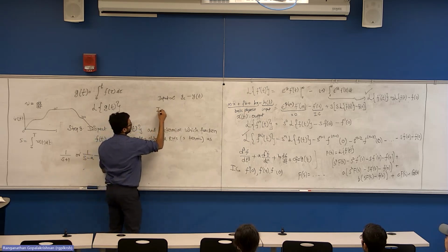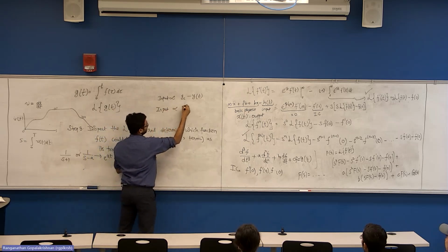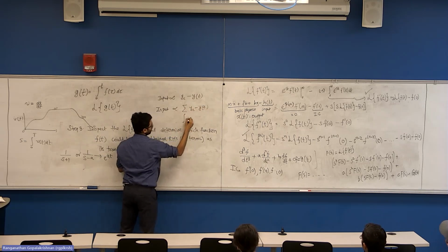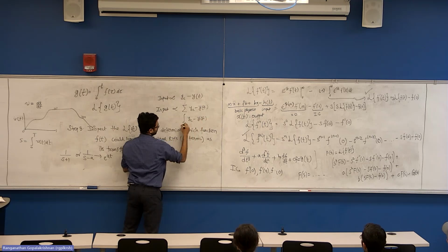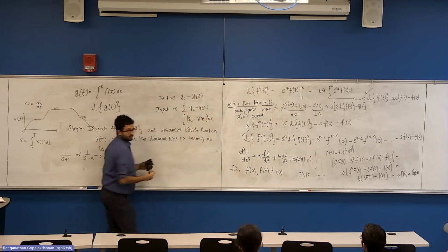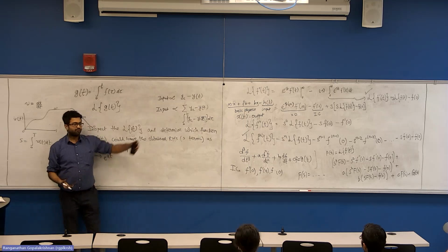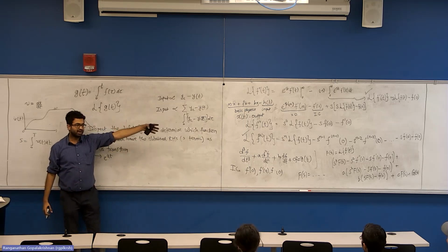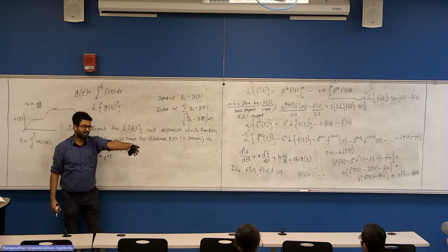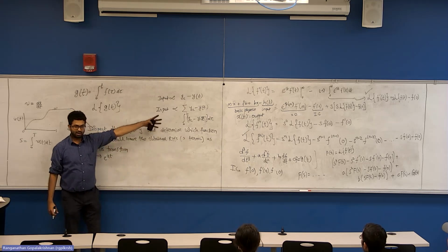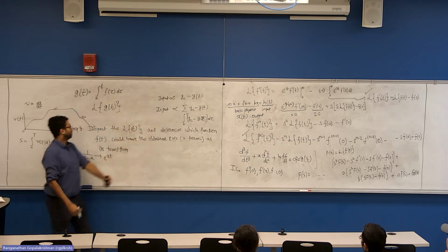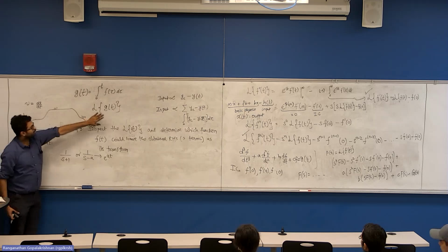If your input is proportional to the sum of the errors up to some point, in other words the integral of the error from say 0 to t, this will be an integral control. Or if it's proportional to the derivative, that is derivative control, PID control. A real controller has all three elements in some proportion, right? So, okay, so how do you get this?